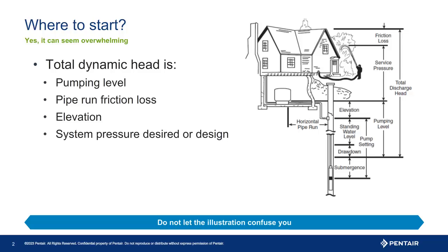So, what is total dynamic head? As you see here, it is friction loss, depth to water, system pressure and elevations. Now it is also important to understand that as a pump professional sizing a pump, our job is done at the pressure tank. We do not do the friction loss calculation for the home itself, but work with the property owner or plumber, whoever is requesting the service, to ensure you understand the need. Now let us further dive into the process.